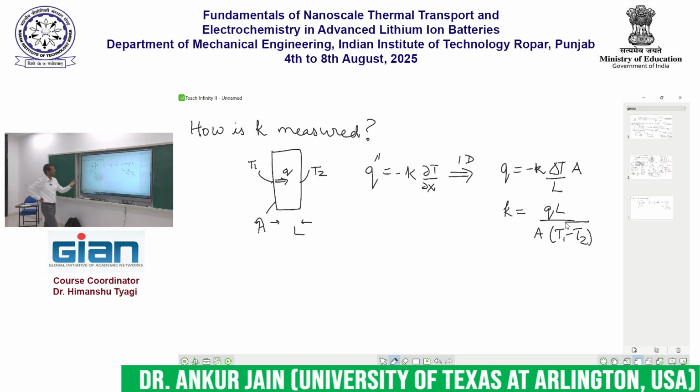I think the easiest to measure are L and A. You can measure the thickness of the body quite easily. Hopefully it is uniform, and you can measure the cross-section area of the body. The challenge comes in measuring Q and the temperatures. So let's think about, as an experimentalist, how will I run this experiment?